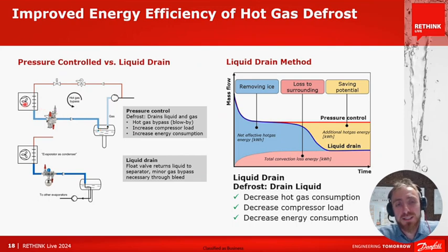However, when there is no ice any longer on the evaporator, therefore no load, then the CO2 gas does not condense and gets out of the evaporator as gas. This gas goes through the valve and back into the receiver and to the compressor, or in other words, hot gas bypass, which is very inefficient for your system during defrost and is penalizing especially systems which are timer controlled. A more efficient way of controlling hot gas is float control, where at the beginning, just like the former one, we have ice on the evaporator, so the hot gas entering condenses immediately.